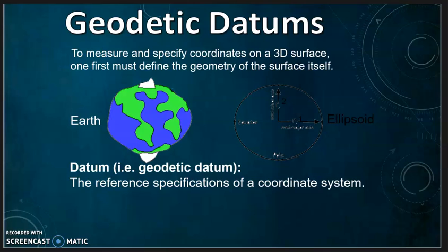You would need to survey a control point at the origin of a geodetic datum where the geoid and reference ellipsoid are perfectly aligned. All of the other survey points reference back to the origin. As the distance increases away from the origin, the surfaces between the geoid model and the reference ellipsoid model become separated, with the reference ellipsoid passing above and below the geoid. Because of this, different geodetic datums were developed for the best fit in different parts of the world.